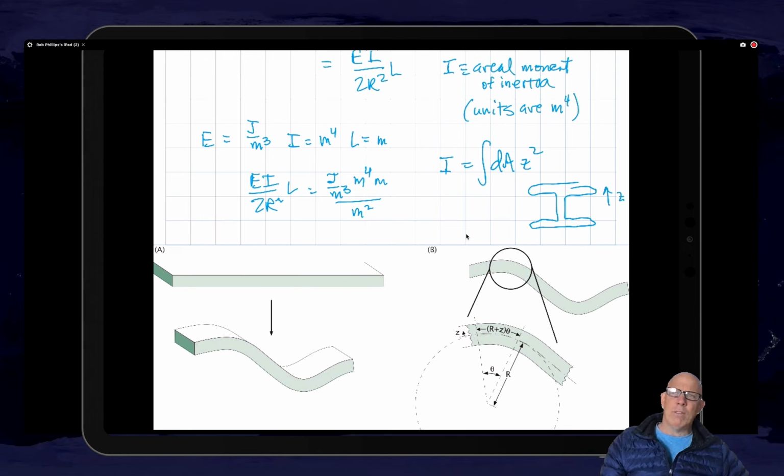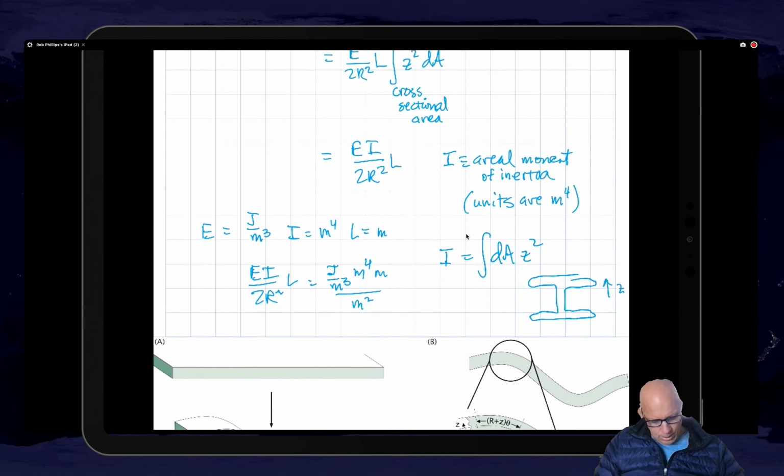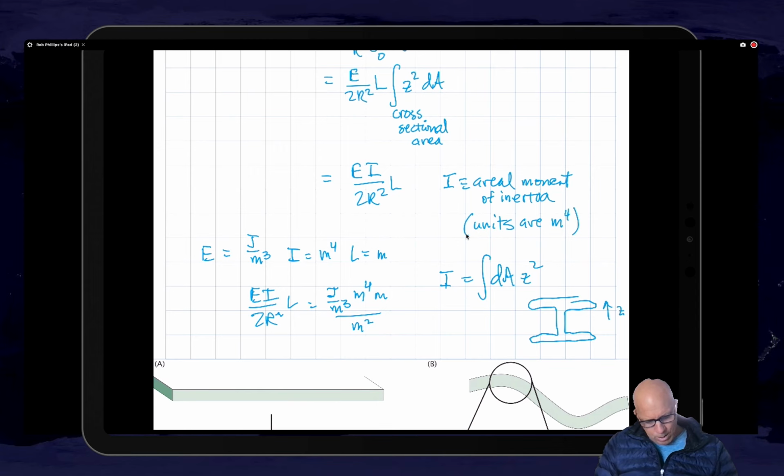So this thing gives extra strength against bending, but not because you made it more massive, not because you made the material E strong with the stronger E, but rather because of the geometry. So what we've done is I've now given you an expression for the energy of beam bending. And what you see is that it's given by E times I. That's the joint parameter that gives you the overall mechanical strength, if you like, or the mechanical stiffness of the beam to bending, and then divided by the radius of curvature.